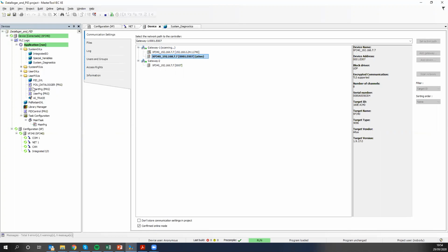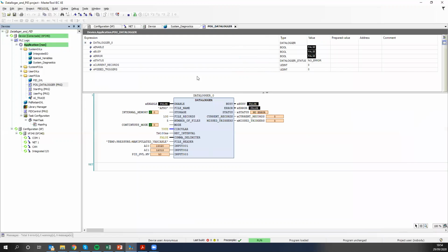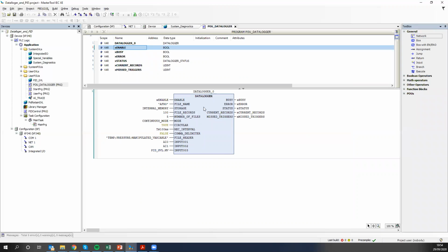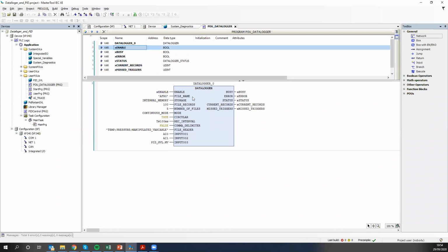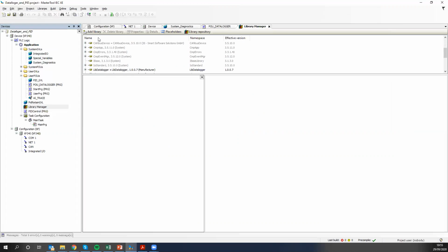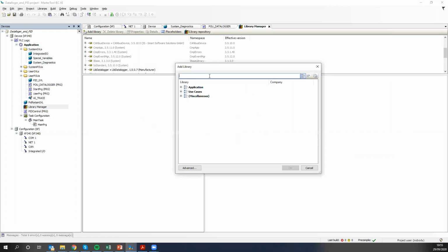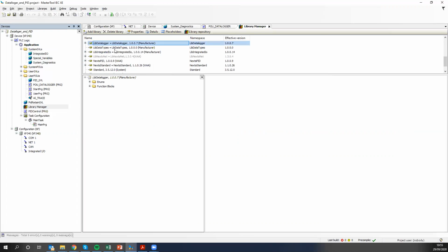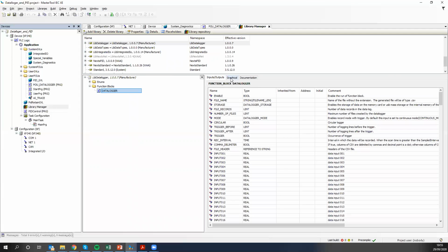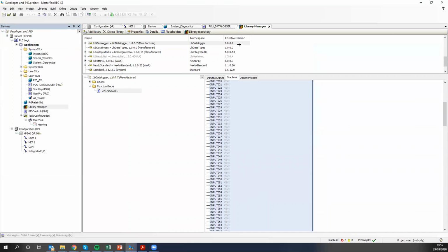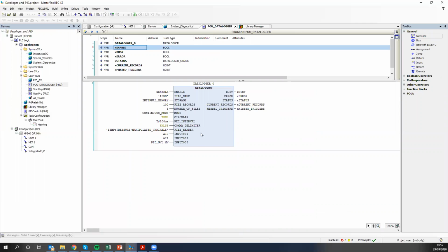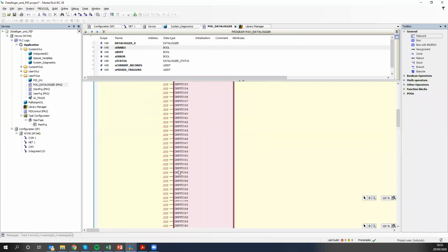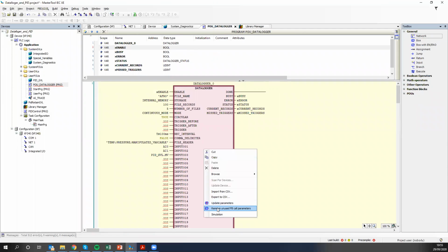So before this training, I created a POU, a subroutine, and let me log out here, just a channel to show you. When I inserted the data logger, of course, I need to insert the library. So I found here the library data logger that is available in the installation. I installed this data logger here, and with this data logger, I received this graphical functional block. And I inserted it here. I will update the parameters just to show you all the inputs that we have. Of course, for our case here, I just insert 3 parameters. So I will remove unused functional block call parameters.